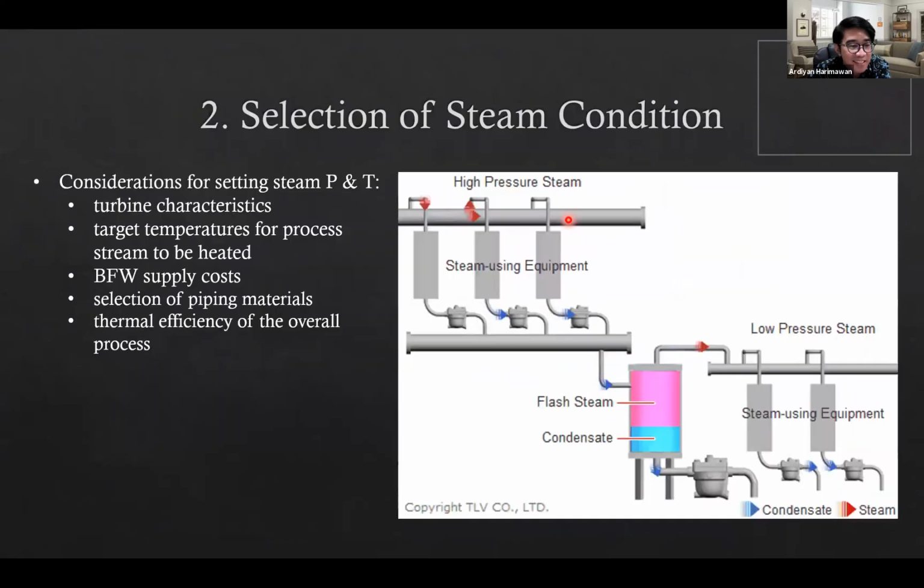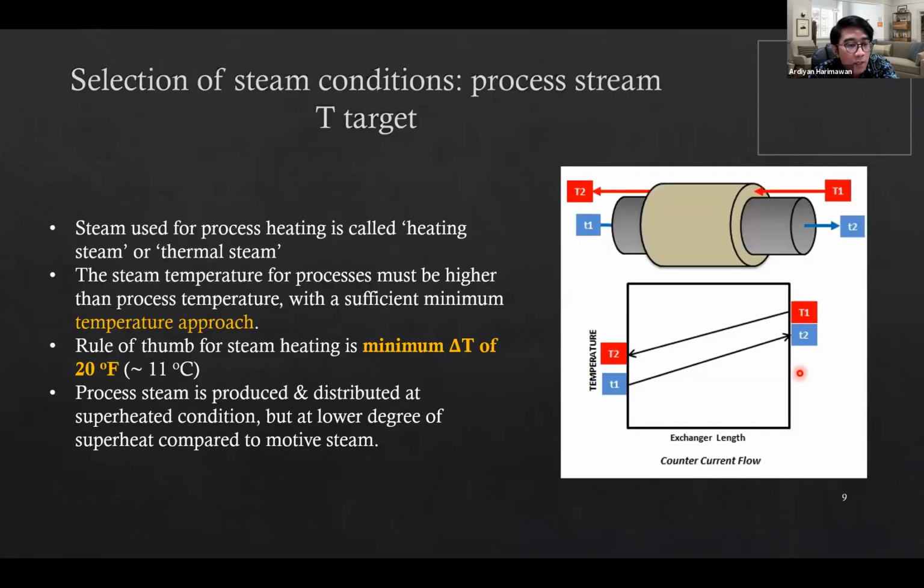And so on. So that's normally how you read the steam ladder. Okay, and this video shows you why we write the steam diagram into the steam ladder. You have high pressure steam that will be used by the equipment that uses high pressure, and of course after being used, it will become condensate, right? There will be some part of the liquid in the steam, so it goes to the separator that will flash the steam, separating the steam from the condensate, and then the steam goes to the lower pressure ladder and is used by the steam using equipment that uses the low pressure. Okay, any question?